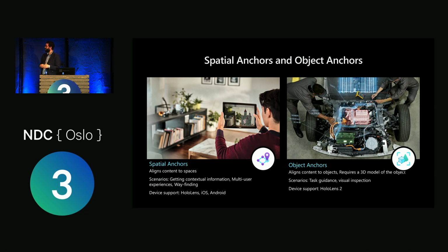So it's a great way to do very high precision locking of holographic content against real-world objects, but there's a size restriction. The objects have to be more than 1 meter and less than 10 meters in every dimension. And they have to be rigid. They have to be rigid objects for you to be able to match against them.